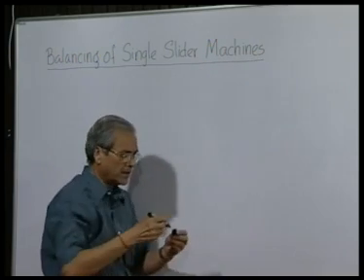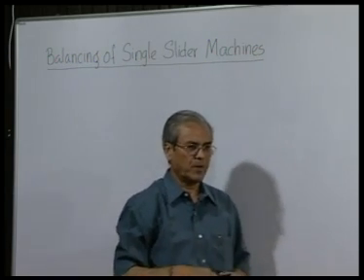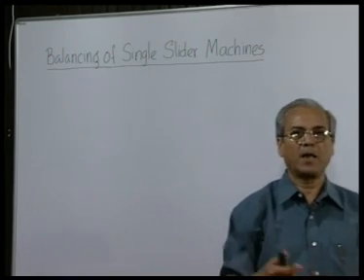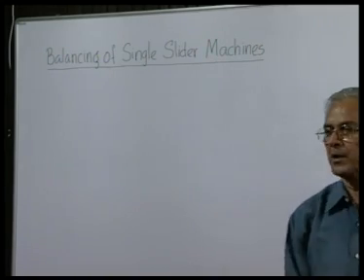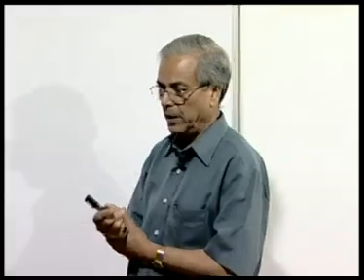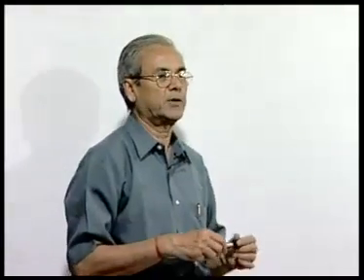These single slider machines are very common, large types of machines, compressors, engines, they all employ this mechanism. So, I think it will be appropriate to take up this particular case and investigate its unbalance, and also to look into the ways and means of balancing the unbalance present.